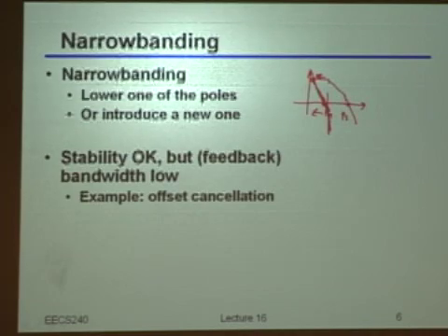So, by the way, this is something that sometimes I would like, and that is applied in some configurations when I, for instance, want to do some offset cancellation. In some systems, offset is so big, or maybe I want to save power and have an efficient design, and so I would like to cancel the offset because otherwise that disturbs my signal. The signal might be too small as well. So I might use this technique, narrow banding, deciding to restrict and decrease my bandwidth, just for the purpose of cancelling the offset.